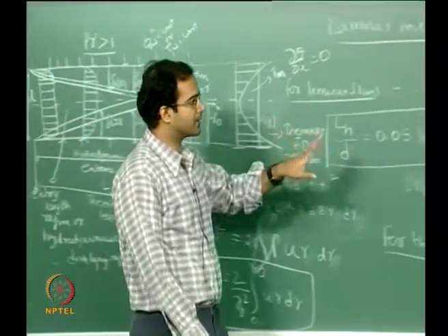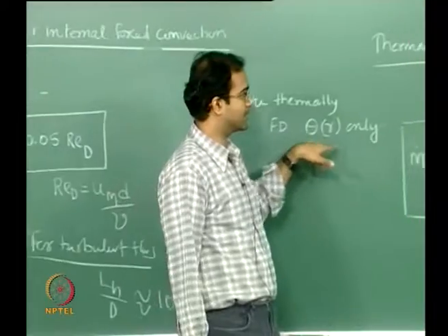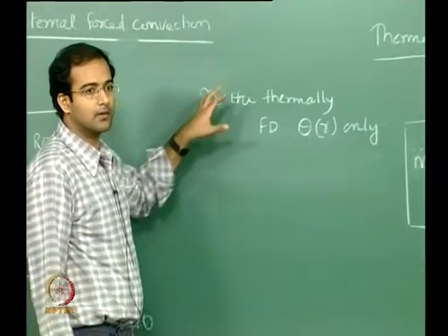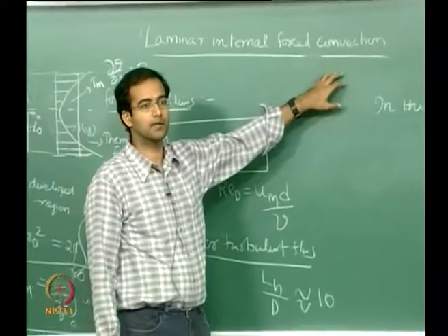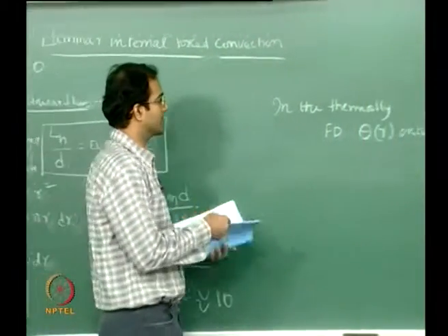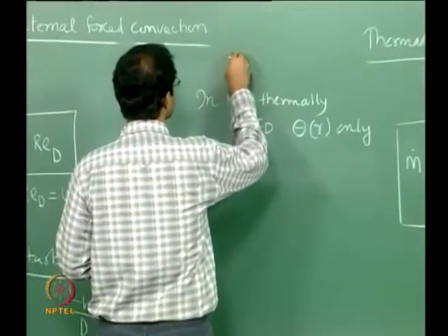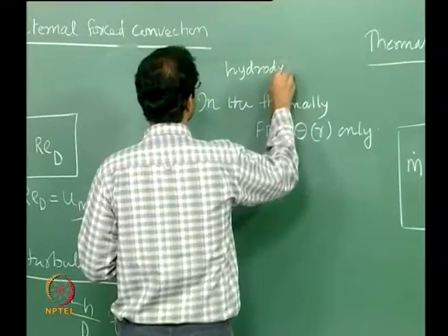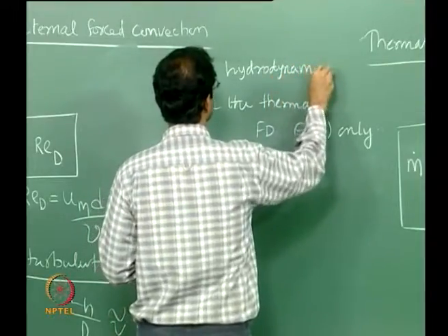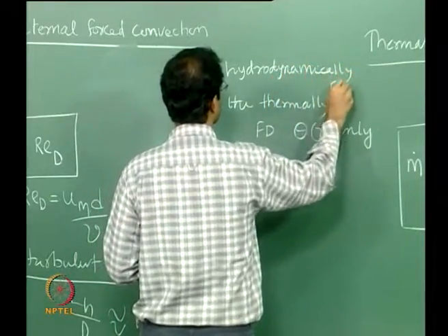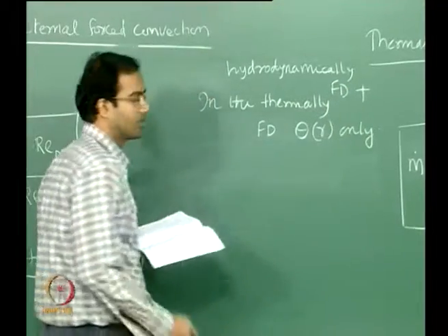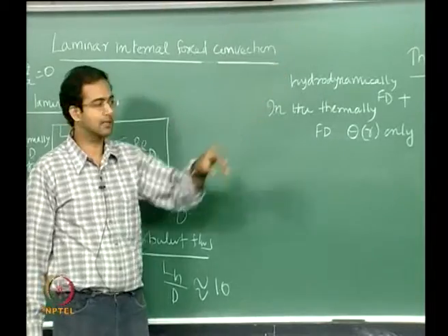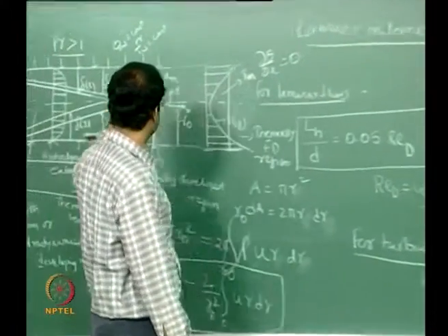Once it becomes thermally fully developed, it is a function of only r, provided your flow is hydrodynamically fully developed. So it should be hydrodynamically fully developed first.